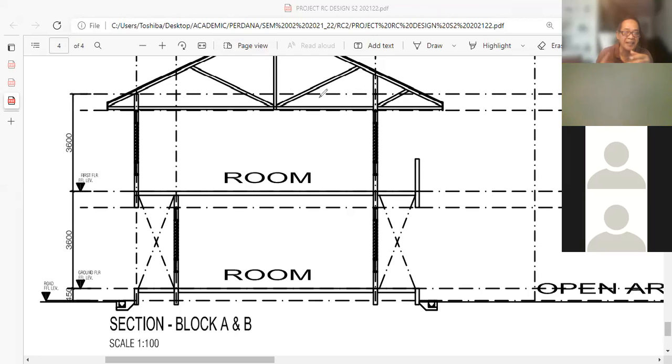By looking at the cross section of the architect building, of the drawings from the architect, we can come to make certain conclusions. For example, like in our case dalam contoh ni, by looking at the ground slab to be a raised ground slab, okay, around 450 mm.